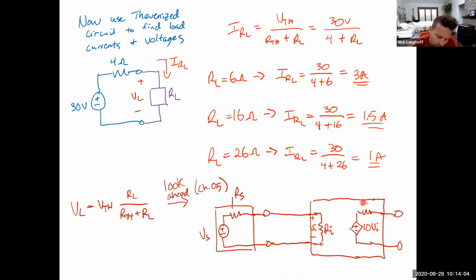And this would be an output resistance RO. The point I'm trying to make is that the voltage delivered to the input of the amplifier, Vi, is not equal to Vs. It's not equal to the source voltage from the microphone itself. It is in fact going to be less than Vs.